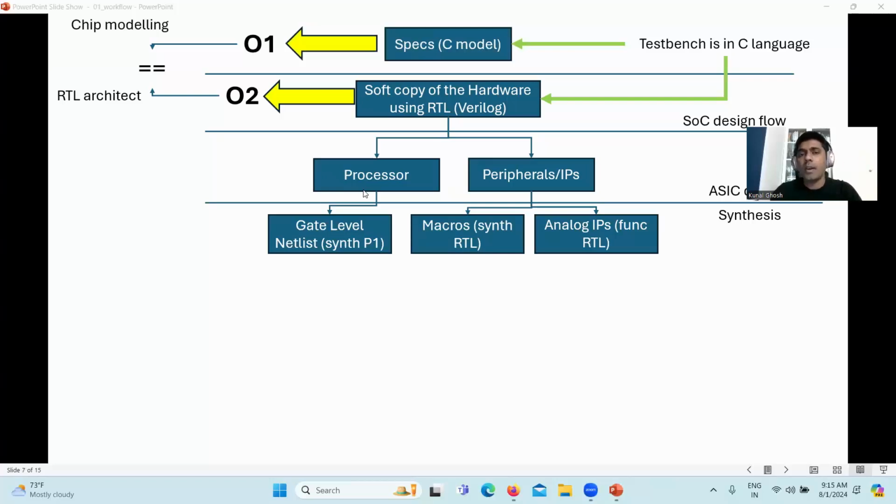Now Verilog is very close to C. It has got some constructs. Let's say it has got a MOS construct. It has got some AND construct. There are some primitives, called Verilog primitives, which are not synthesizable to gates.